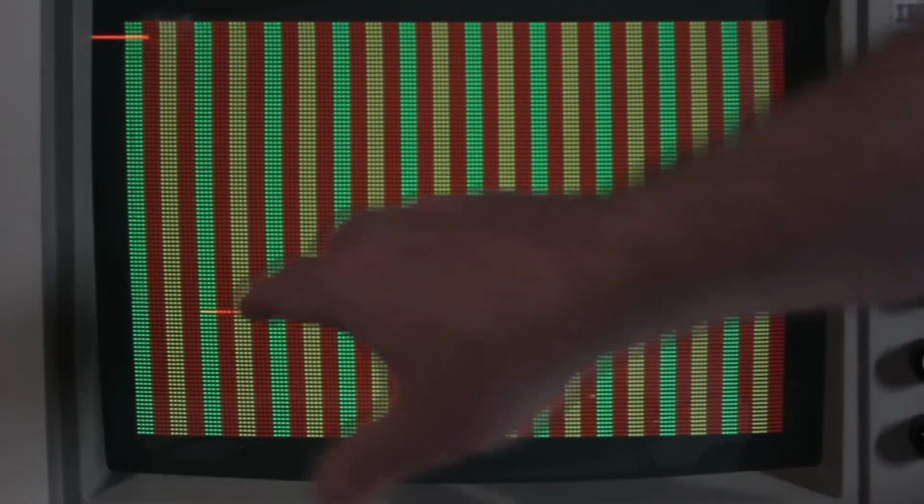Well, here's the result of that. It's perfectly still, there's no jitter, and it's doing the background color change at exactly the same point every frame. And not only that, if I go back to DOS, no parity error. It's doing the DRAM refresh perfectly. But now we have another problem to solve.